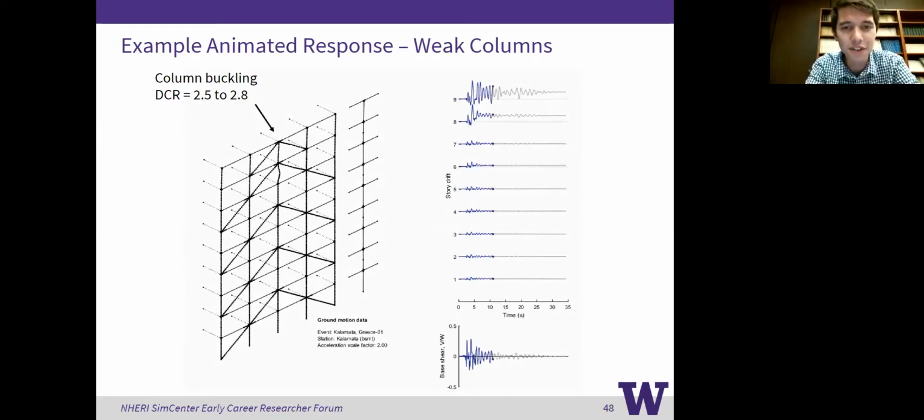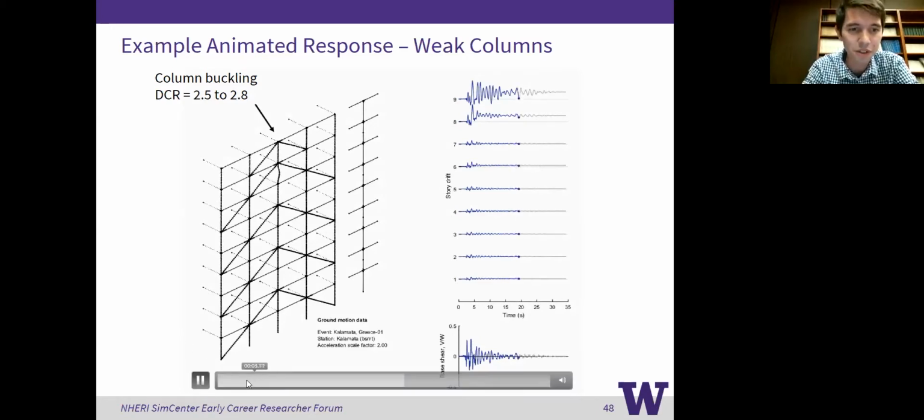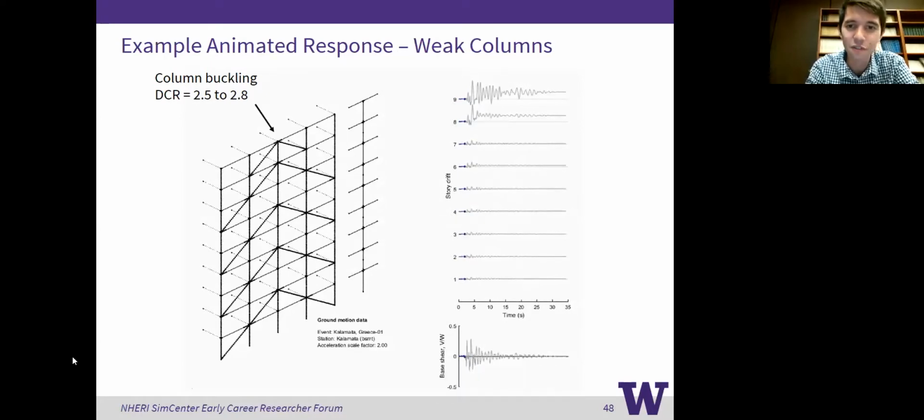And if we can take all these different ground motions, because we have information in the OpenSees API about the node locations and everything, it's really easy to build this simple preview model and then adjust it for the different deformations that we're recording in the analysis, okay?